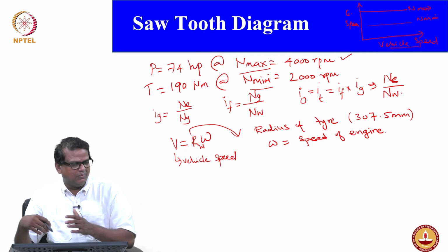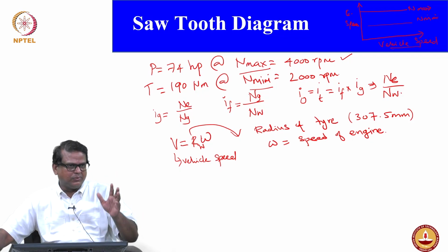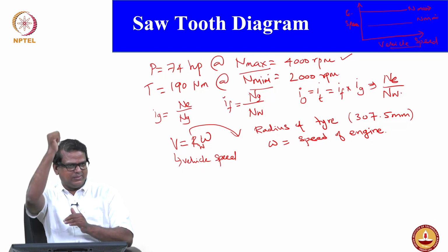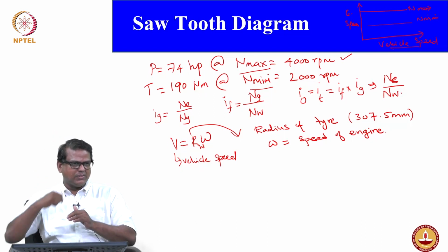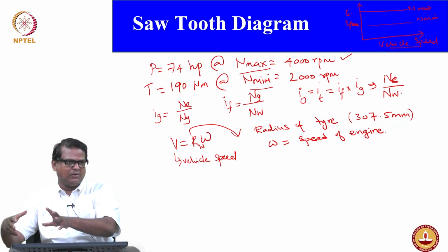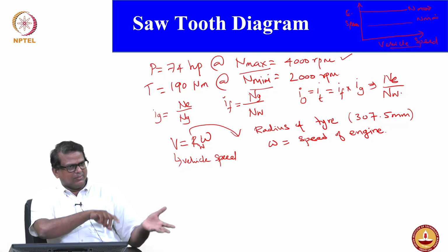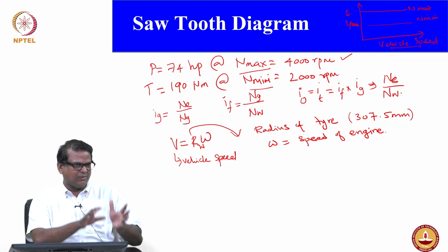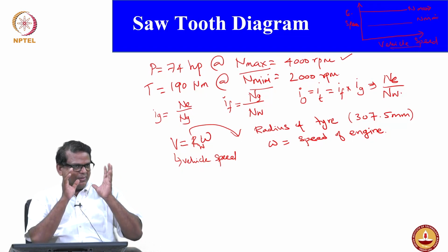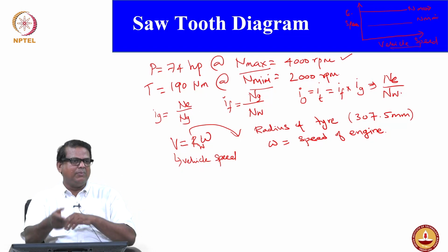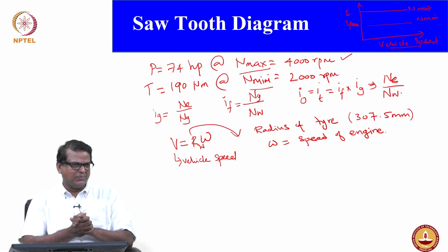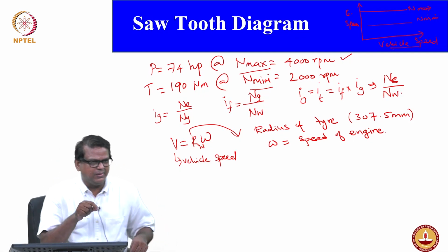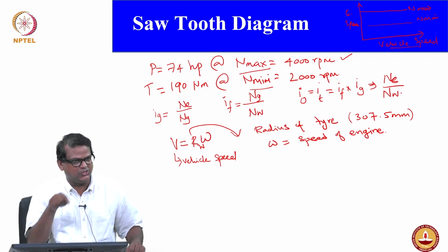It's a good question. The engine has reciprocating, linear motion. The linear motion is converted into rotational motion by the wheel. So the omega, in fact, corresponds to the wheel rotation, the angular velocity of rotation, but we are getting it from the engine. That is why I mentioned it as the engine speed. Good observation. That is the reason we are taking it from the gear ratio.